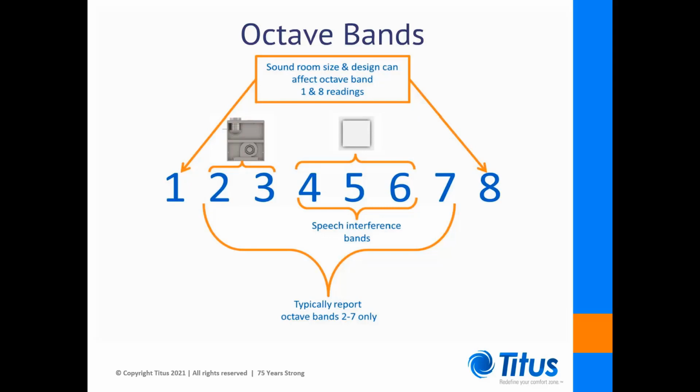When a fan motor is running, you can be sure that the NC level will be set in the 2nd octave band, although it's possible that it could shift to the 3rd octave band at higher speeds. This fan noise tends to override any contribution from a primary inlet damper on a fan-powered unit.